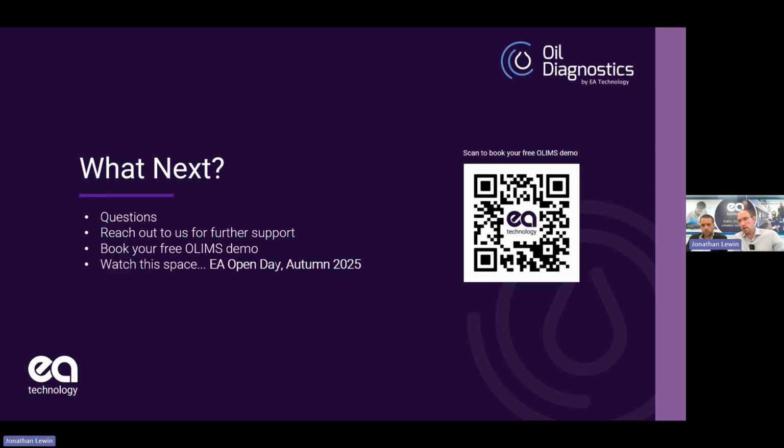When we're doing the interpretation, on the sample label and the report, it's all to do with the type of oil. So when we've got that type of oil, it's about understanding: are they any better than minerals? It depends. It depends who you speak to, and it depends on the application. We have assets that are 60 to 70 years old with mineral oil in and they're still going strong. It depends on the asset quality as well as the oil quality.